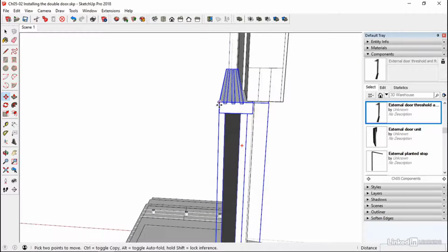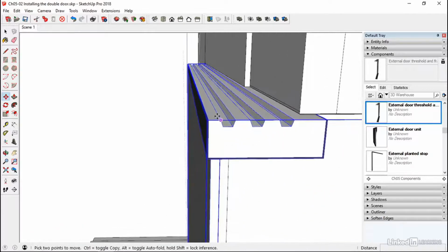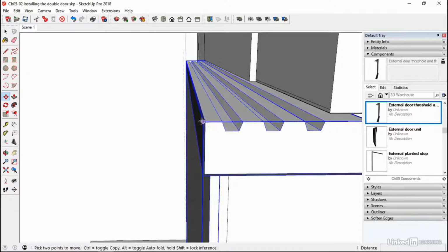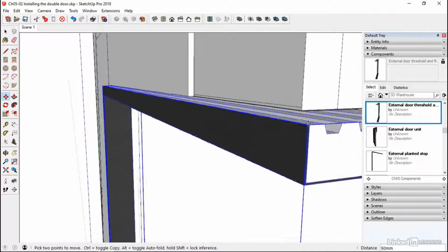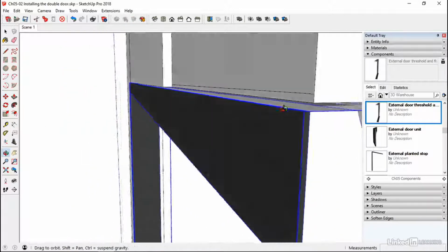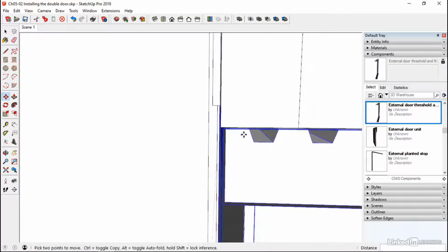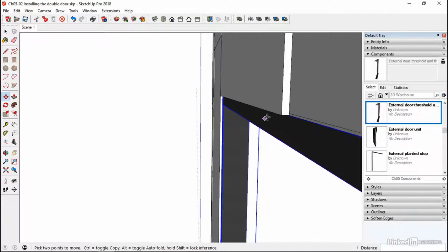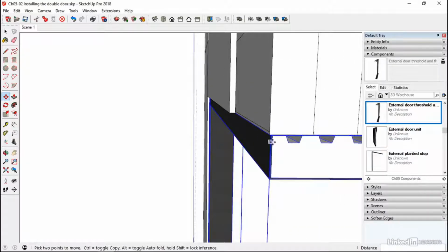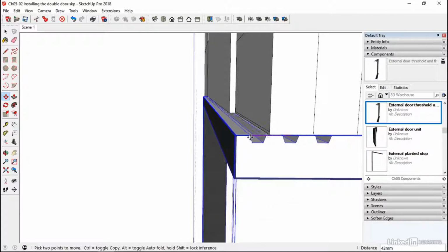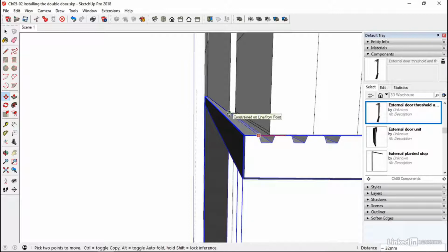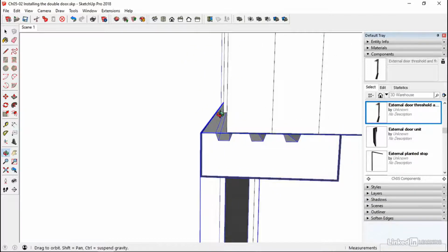And then to position it, if we roll into this bit and find that external corner, the grey one, and then come into our membrane and just sort of attach it to there. Now we're going to sort of pick it up at this point. This might be temporary because I can't remember how thick this needs to be. So it's better if we kind of position it now and then maybe move it back a bit later. So we'll pick that corner, come on the red axis, and just lock out and pick this point here, which is the outside of the drywall.